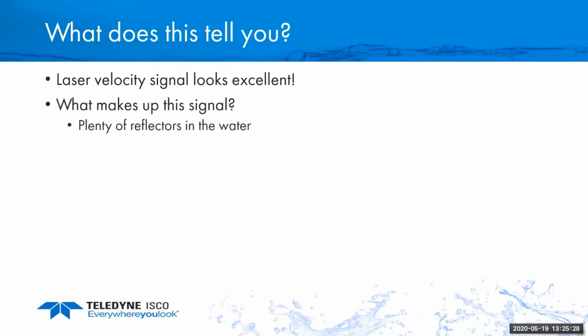Why? What makes up that signal? It's got to have a couple things. One, it's got to have reflectors in the water. Most of these are used in wastewater, so there's typically plenty of stuff to reflect off of, but there are a lot of times that you may have very clean water. Well, would this thing work in clean water? It really depends on how much entrained air is in the water. What do we have in that water that will reflect that laser beam back?